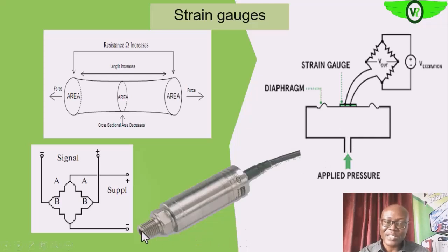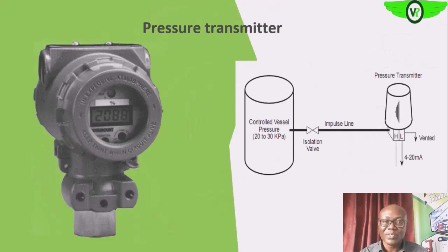Okay, so this is an example of the sensor. Here is connected to the process. The process fluid stretches the diaphragm. Okay, we have the Wheatstone bridge, the power supply and the outputs, they come in through these cables. Okay, and then this is fed into the system that will give us either a direct reading or for control purpose.